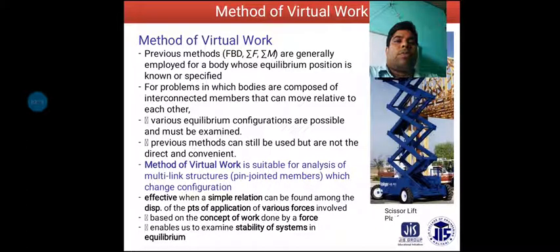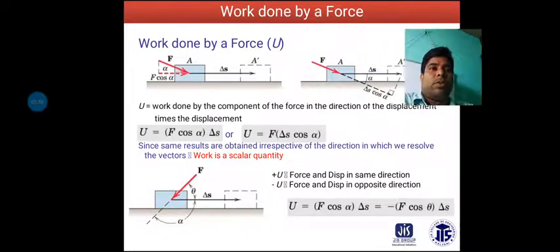Now the method of virtual work is suitable for analysis of multi-linked structures, that means pin jointed members with changed configuration. It is also effective when a simple relation can be found among the displacements of the points of application and the various forces involved, and it is based on the concept of work done by a force.